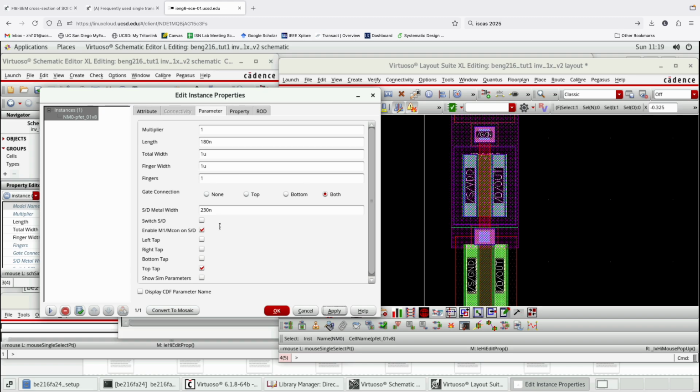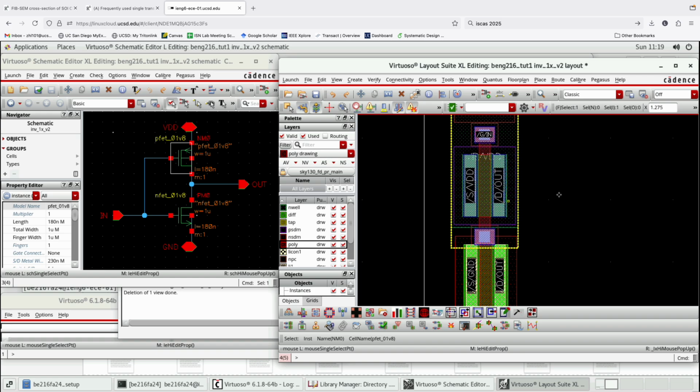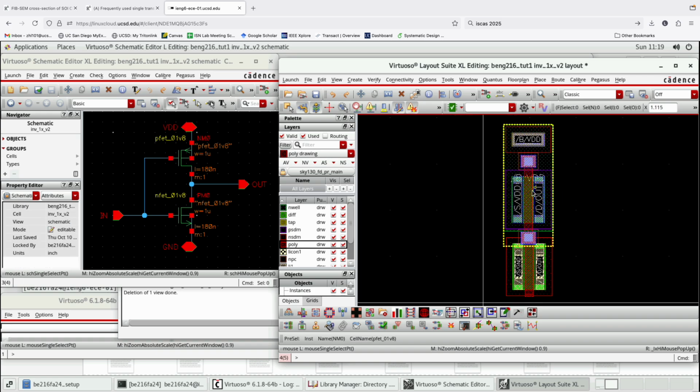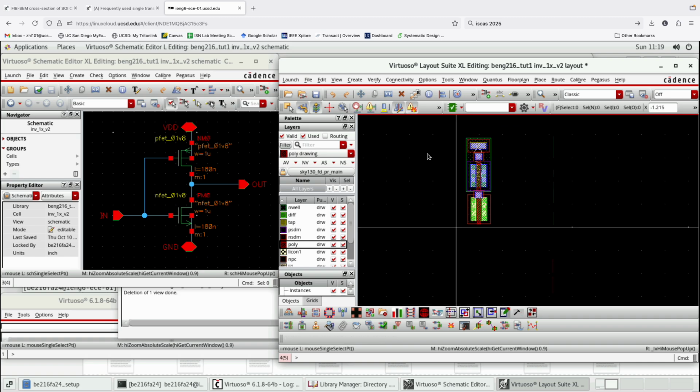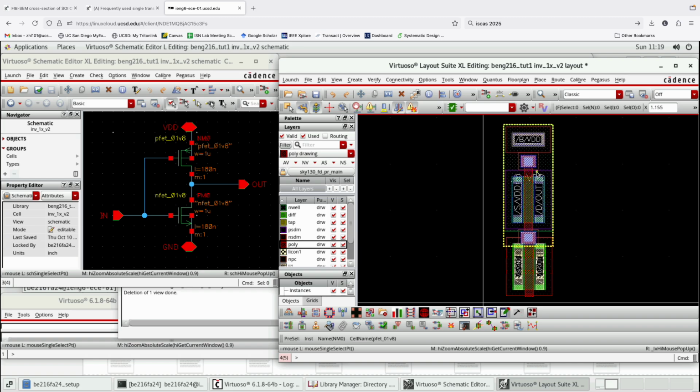But then even before you play around with these, you have to think about how you would like these transistors to be connected. How would you picture your overall layout is going to look like? Because in our case we have a very simple inverter, with PMOS on the top and NMOS on the bottom, we would try our best to make the area after layout as small as possible.